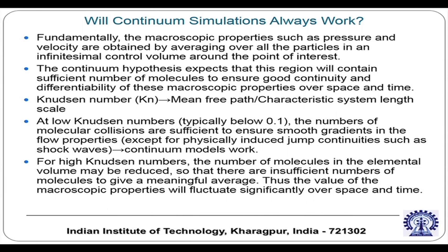However, if you go for higher values of Knudsen number, then the continuum nature of the flow is destroyed and the discreteness of the molecular entities becomes important. When this discreteness becomes important, you have to use typically either molecular dynamics or a Monte Carlo based simulation, which is known as direct simulation Monte Carlo or DSMC.